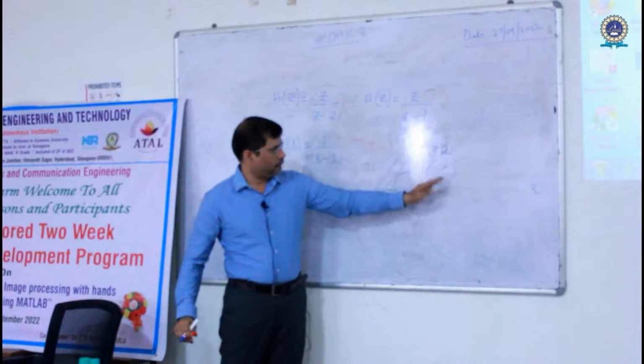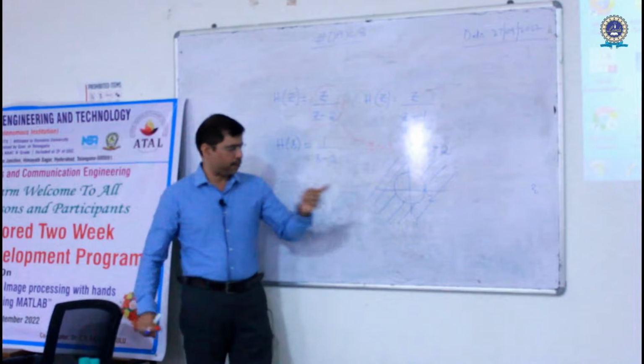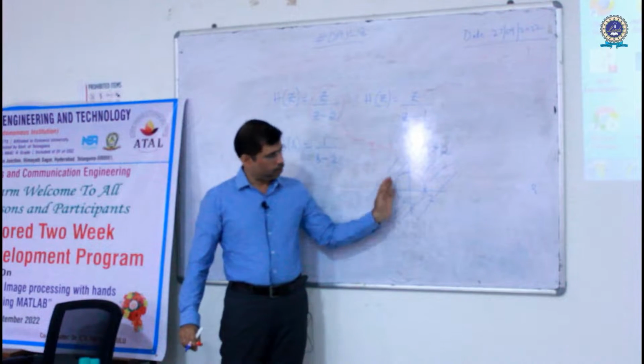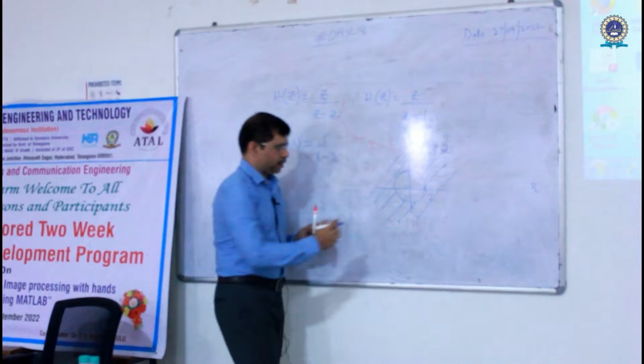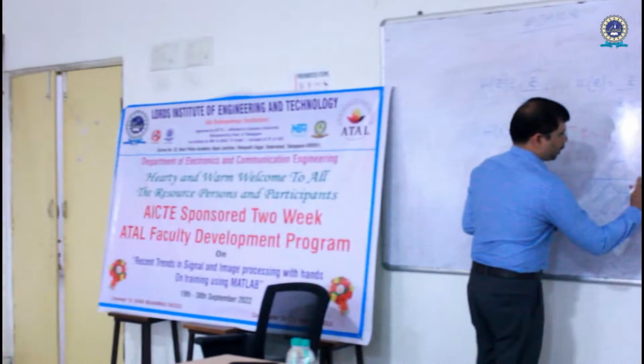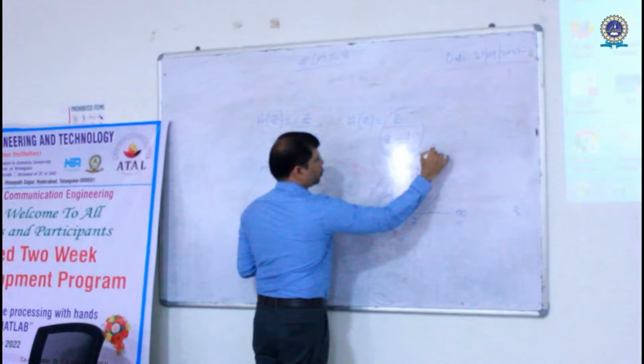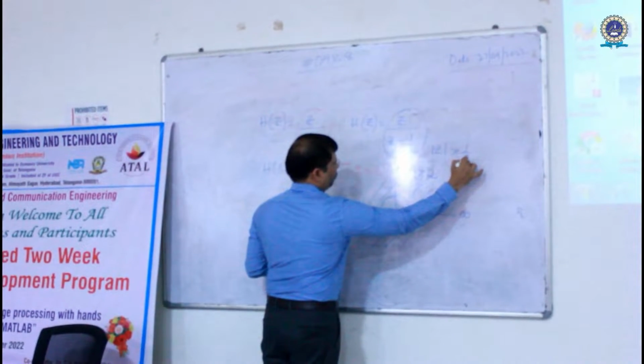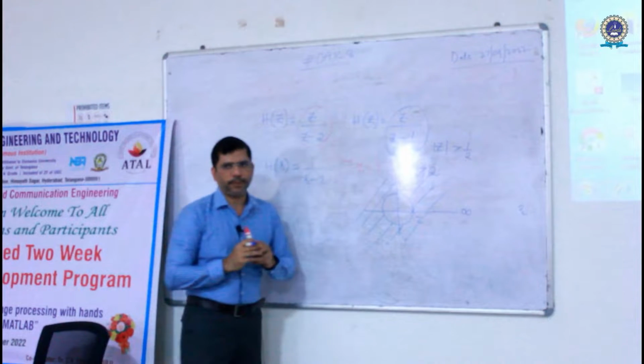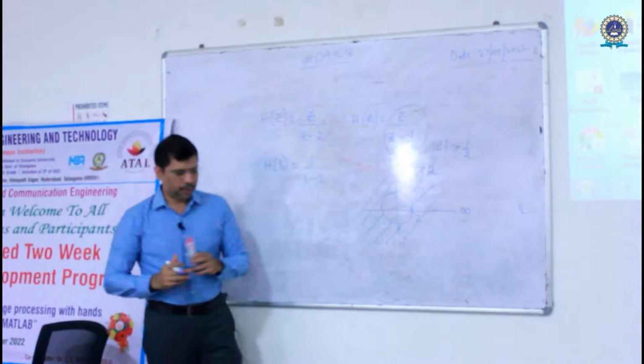So you have outermost pole, because I have only one pole, so therefore I would say that outermost pole is nothing but 2, outside. So therefore, when I consider this from 2 to infinity, clearly you can understand that you are not covering 1. So therefore there is no unit circle here. So therefore you can say that this is an unstable system, right? So Z by Z minus 2 happens to be an unstable system, but whereas if you look at this Z by Z minus 1 by 2, assuming that this is causal, so you have mod Z greater than 1 by 2, wherein that covers 1.